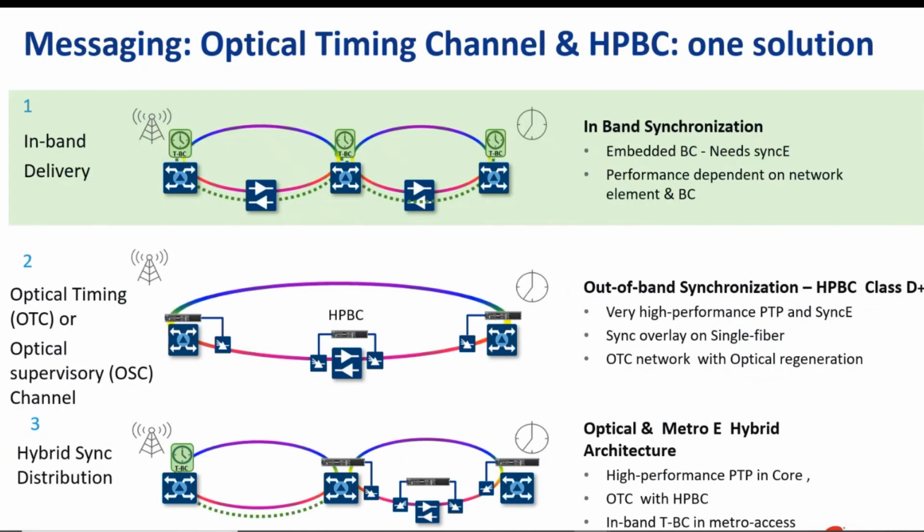This illustration shows some examples of how to do optical timing methodologies. We can do timing in band over optical networks such as DWDM or ROADM products. If we look at number 2, we can also do timing over DWDM networks using external high-performance boundary clock functions. In many cases, the optical equipment in the networks does not support embedded timing. So in this case, we would send the timing around the DWDM muxes through a high-performance boundary clock that could be the time provider 4100 to create our virtual PRTC function at the other end of the optical network.